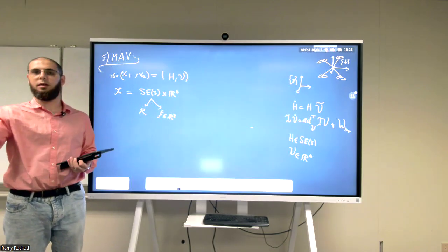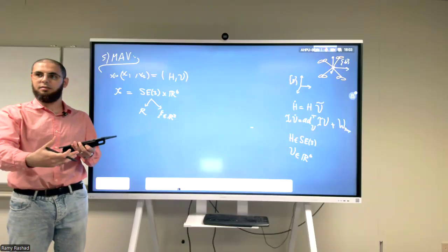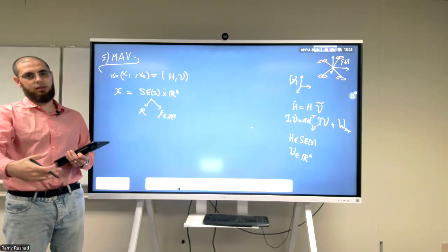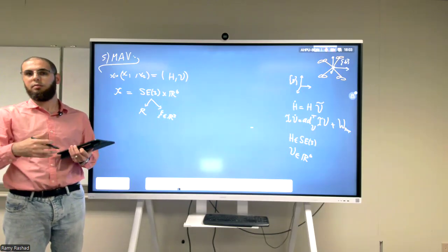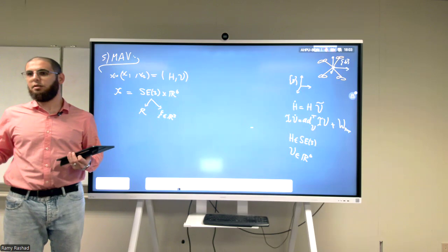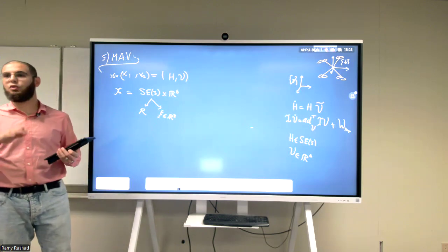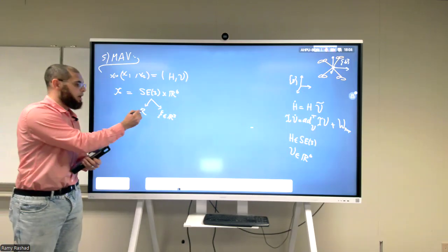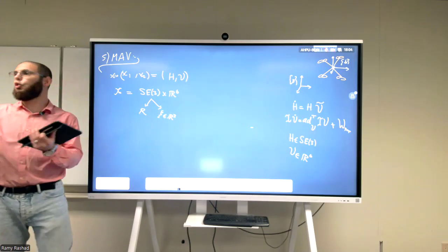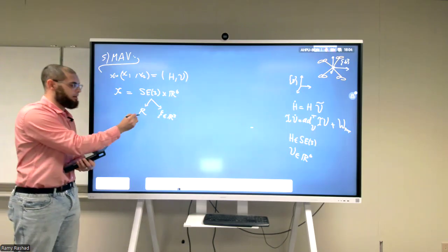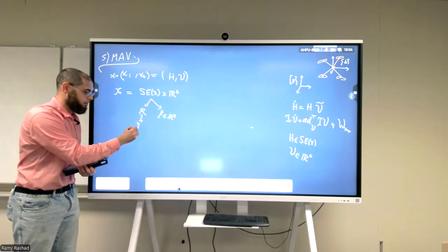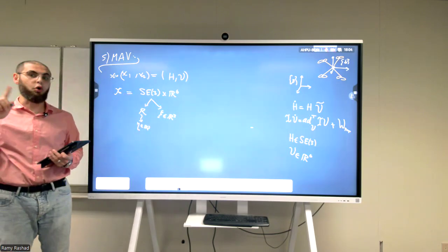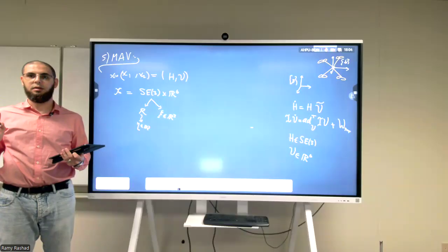The most popular one is that you do rotation around the Z, you call it the yaw, then rotation around the Y, you call it the pitch, then rotation around the X, you call it the roll. Yaw, pitch, roll convention. But it's not the only one. You can have 21 different versions, including that one. So the R itself, I can locally, but not globally, represent by some sort of vector of 3 angles. And yes, of course, I can say it's R6. But globally or locally, it makes a difference.